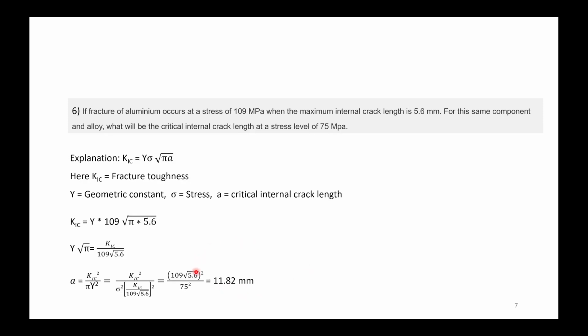Now you can check this as well, because if you made some mistake in calculating, then using the theory, if you are increasing your stress, then your required critical crack length should go down, because it will be inversely proportional in root.